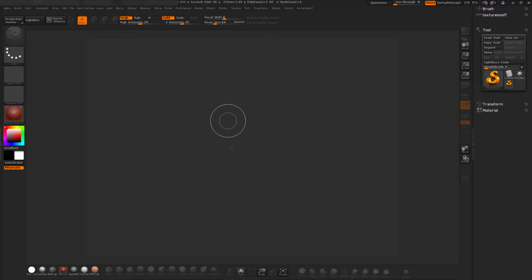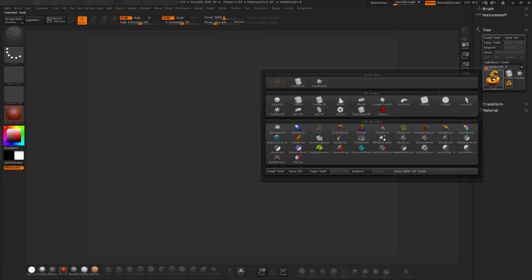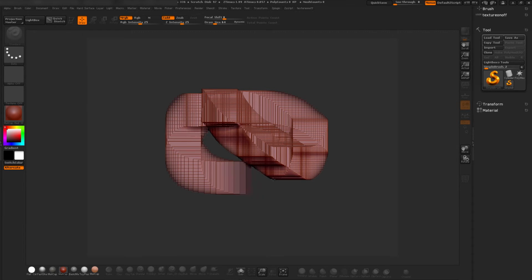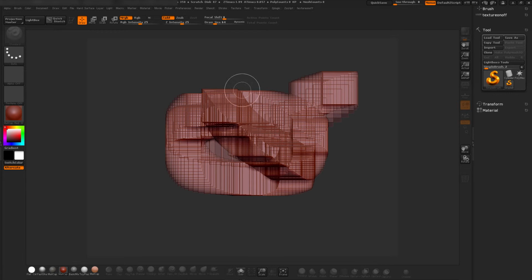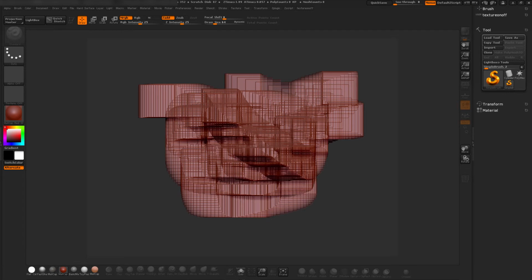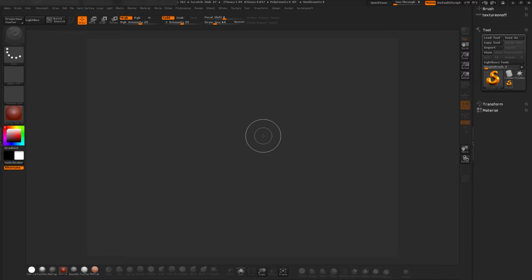So we want to add an item to here. Now if you don't grab a tool from the tools palette and you just decide to left mouse button click on here, you'll get this and you'll be like, why can't I do anything? That's because with ZBrush you need to create a tool and then you need to go into edit. Now to get rid of this big mess that's happening here, you can press Ctrl and N. So hold the Control key, press N once, and that will clear the canvas.